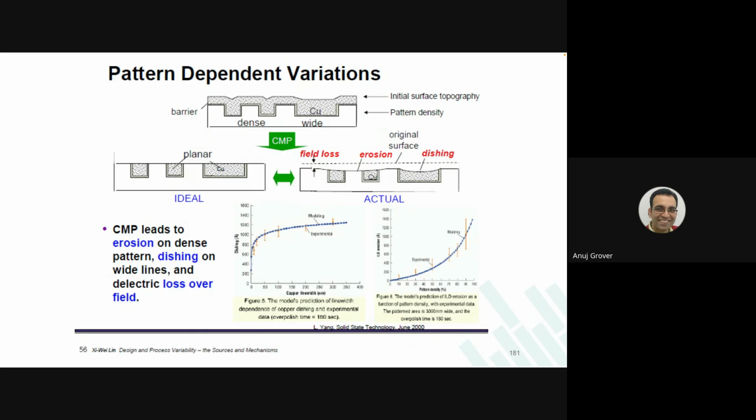How many of you noticed that when we were talking about this constant negative bit line driver, I had mentioned, and it was also written in the paper, that the capacitance of the replica bit line is 2 CBL? How many of you noticed that? Oh, just a few of you. So now I want to have a multiple of CBL, not exactly CBL. I have to double the capacitance of CBL.